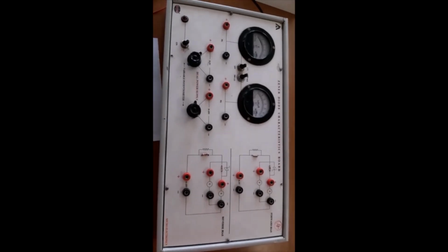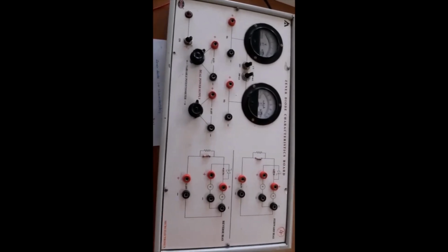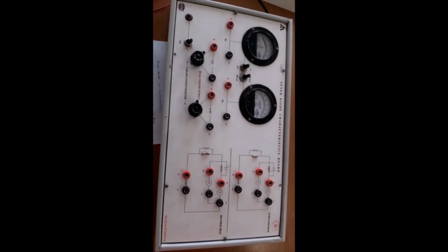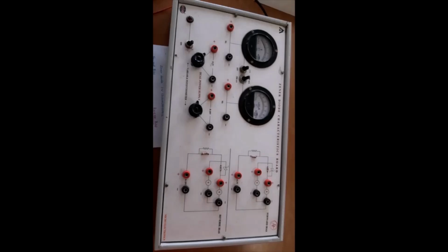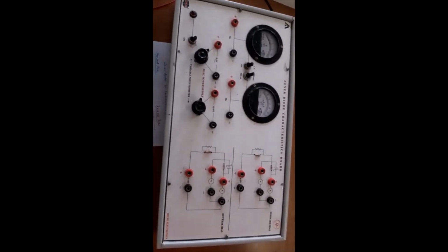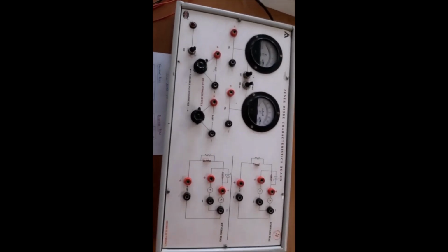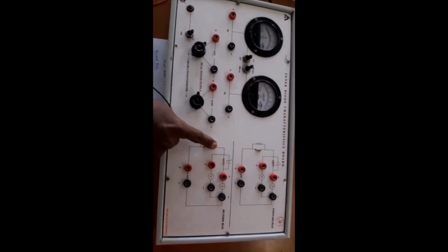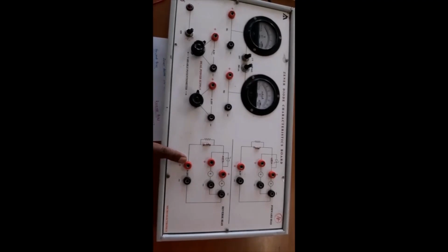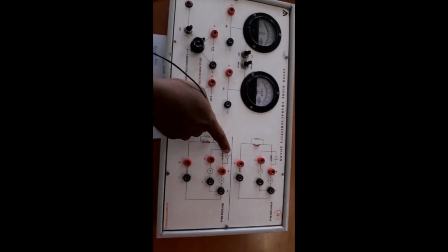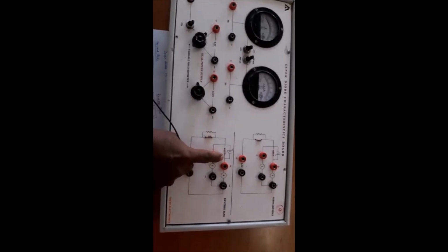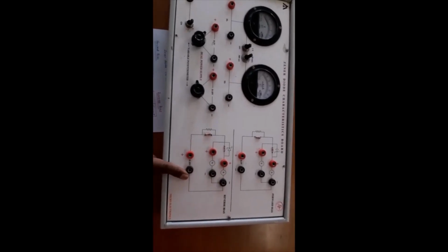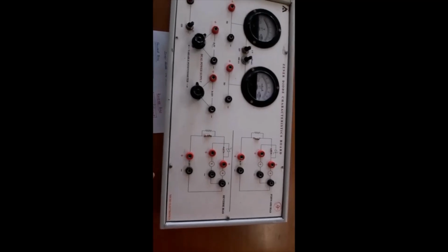Now we will do the reverse bias experiment. I have removed all the connections from the forward biased condition. I switched it off. And now you connect, this is the Zener diode and this is the negative part which has gone to the positive of the battery, and this is the positive side of the diode which has gone to the negative side of it. Therefore, the Zener diode is under reverse bias.